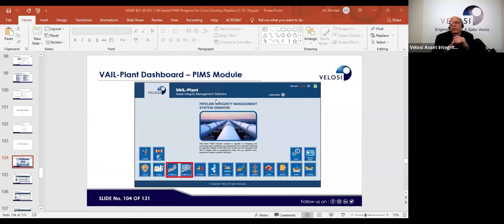Unfortunately, there is no effective inspection program which can be followed for the integrity assessment of flexible risers or non-metallic pipe. As per our experience, there is no effective inspection program other than visual inspections, because no NDT technique can be applied. Hydro test cannot be done because the riser is already in operation.